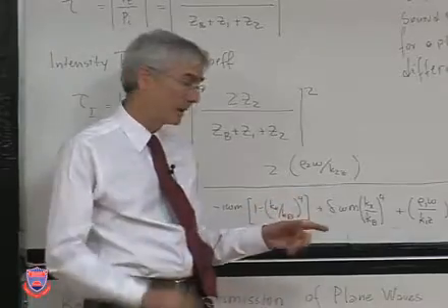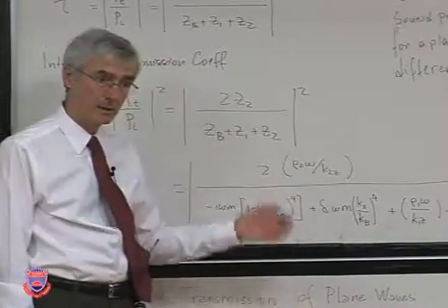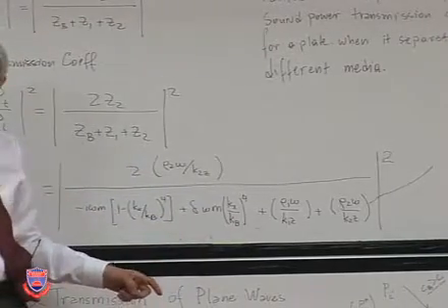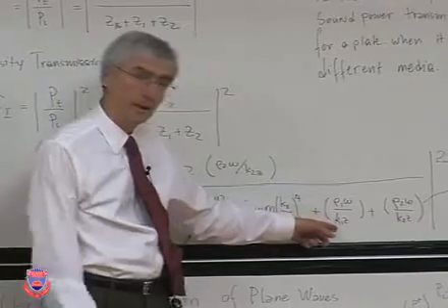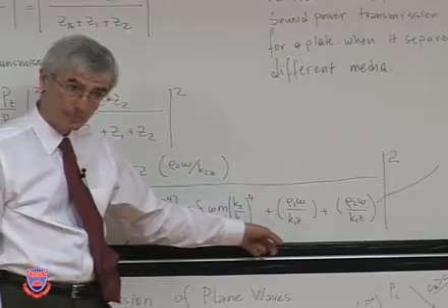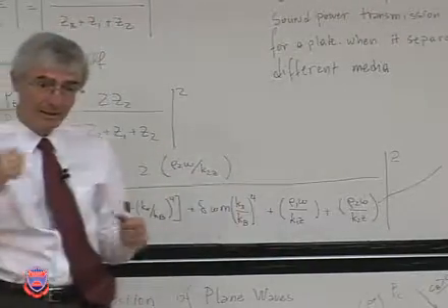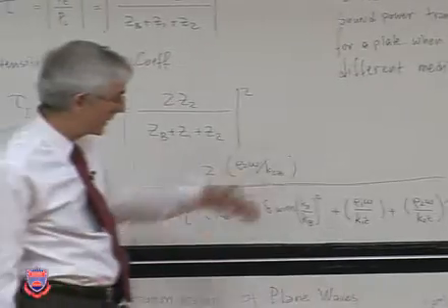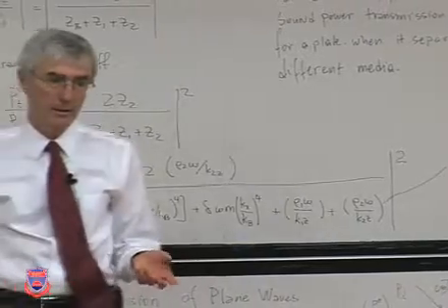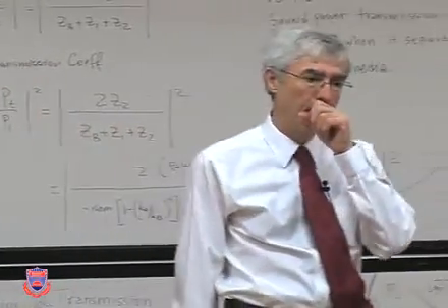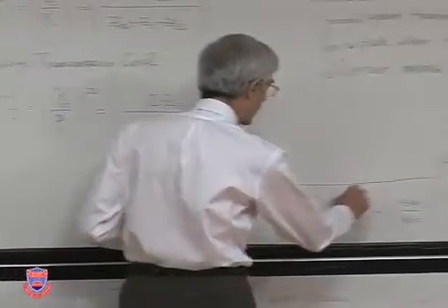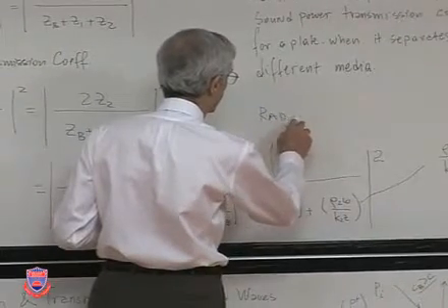So some of the incident energy excites the plate. As a result, there's plate damping. Okay? Just like what I demonstrated earlier, which you didn't see. And what do these do? They radiate sound away. Some of it is reflected back. Some of it is transmitted to the other side. So radiation of sound is a damping. In fact, in making calculations, radiation damping is a term. Okay? So you can call it radiation damping.